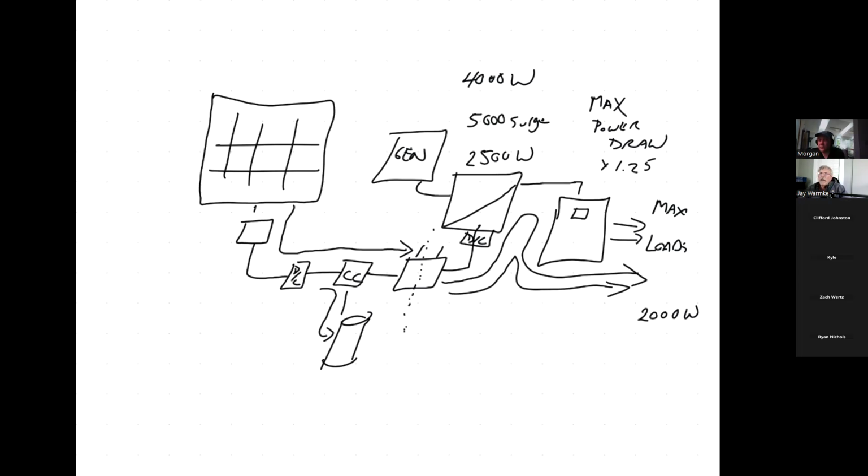Contrarily, if you've got a generator built into this system, it's generally going to be generating AC power. And it hooks into your inverter. And that inverter, if it can accept a generator, is usually called an inverter charger. The reason for that is because all that generator is doing typically in these systems is recharging the batteries.